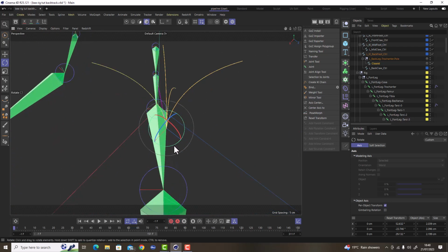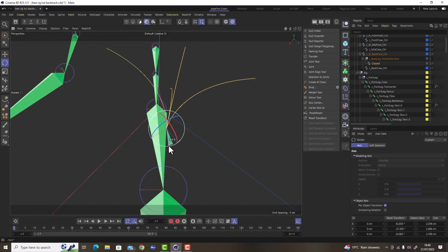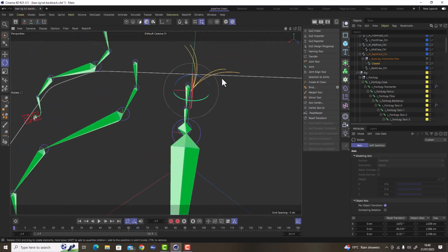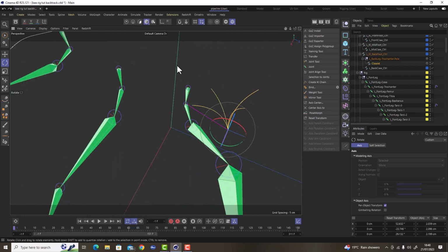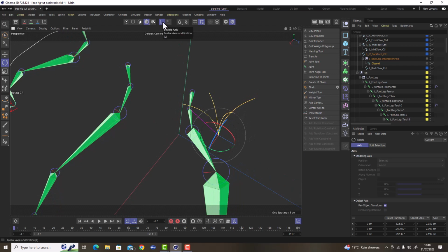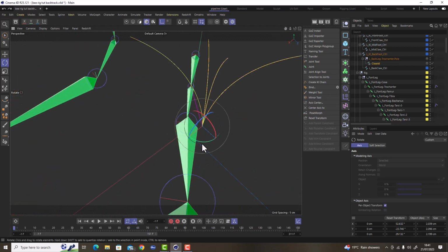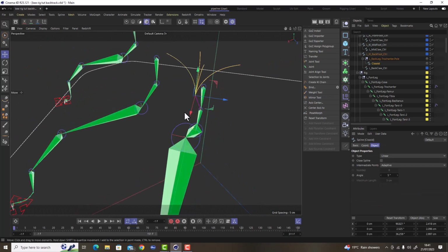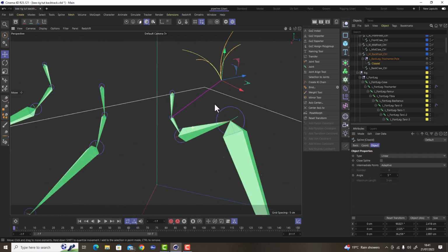So what I'm going to do is rotate this with the shift key held down 45 degrees. And you notice that when I do this, it's actually shifting our geometry to the controller out of place. So in this particular case, I want to do this to the actual locator's centered position orientation by selecting the axis tool and then doing it, and then it won't move the object itself but only its position. And I'm going to rotate this until it says 45 degrees. Okay, you can see that that's given us the exact position that we need.